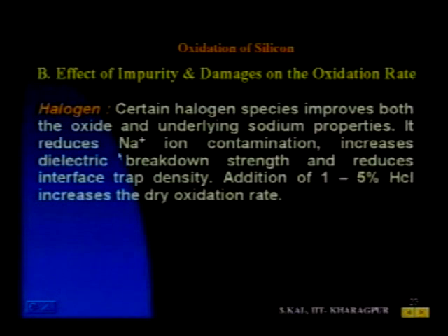It reduces sodium ion contamination, increases dielectric breakdown strength, and reduces interface trap density. It has been observed that 1 to 5% HCl increases the oxidation rate.